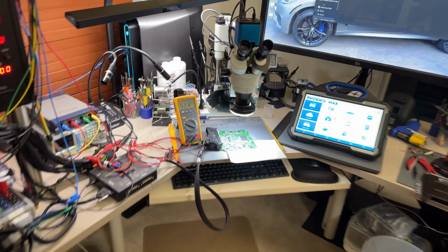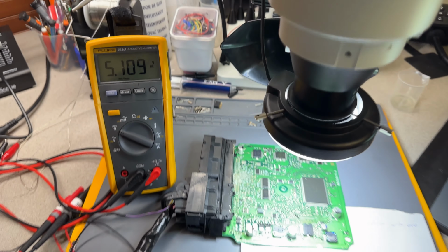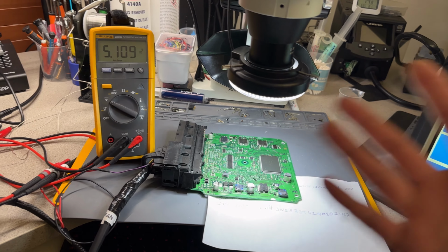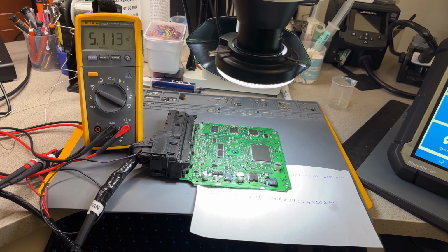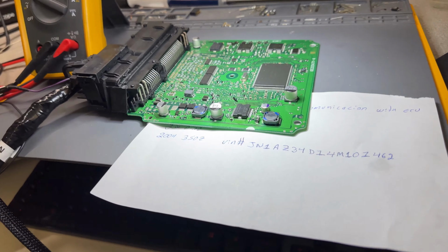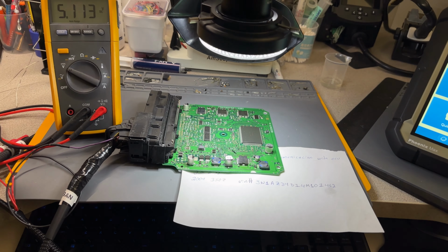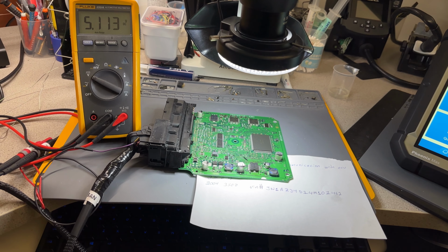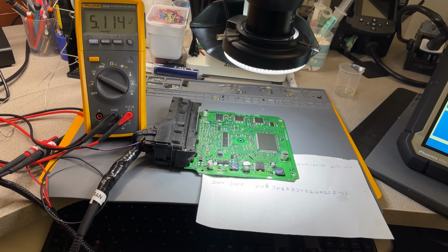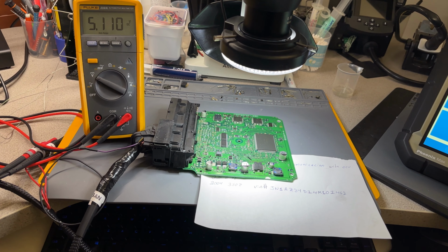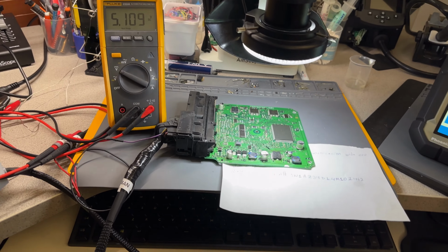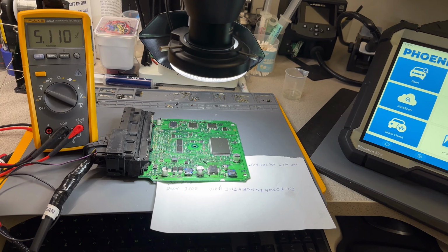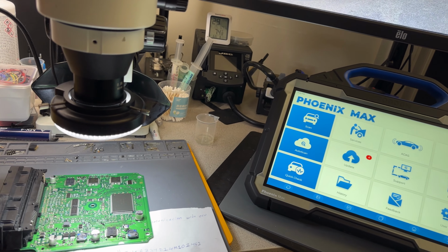I already replaced the component. In components, it's actually really easy. If I find something that is not what I have recorded in other videos, I will show you that. But you will see in the pictures, I usually recommend to replace capacitors, voltage regulators, the diode and capacitors for the CAN network, and the two ICs for coils and injectors, which are the ones on the back, for those that don't know. All right, so let me just show you some pictures.